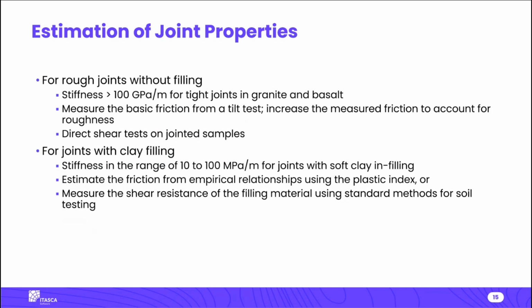Okay, so now the question is, how do you get the joint properties? The stiffness is quite challenging. Most people do not know what the normal and shear stiffness is for the joints. Note that the units for this is stress over distance. So if you're doing metric, it's like pascals per meter or gigapascals per meter or something like that.